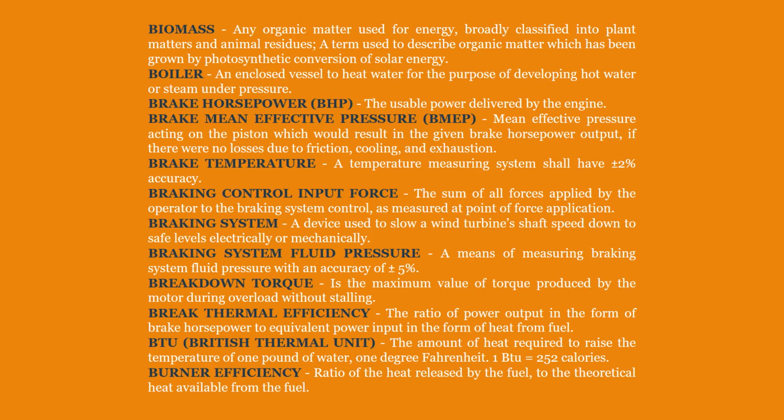Brake mean effective pressure, BMEP. Mean effective pressure acting on the piston which would result in the given brake horsepower output, if there were no losses due to friction, cooling, and exhaustion. Brake temperature. A temperature measuring system shall have plus or minus 2% accuracy.